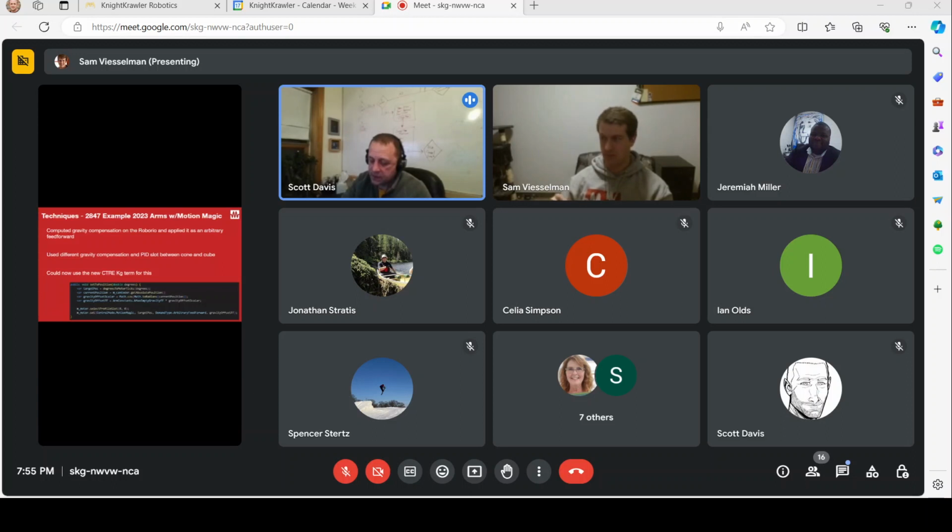So you would need to figure out your maximum voltage you wanted to apply. Let's say it's 10 volts, and you had to go 2,000 ticks. Maybe the right place to start would be 10 divided by 2,000. Yep, I'd say that's good. That would be a good place to start.